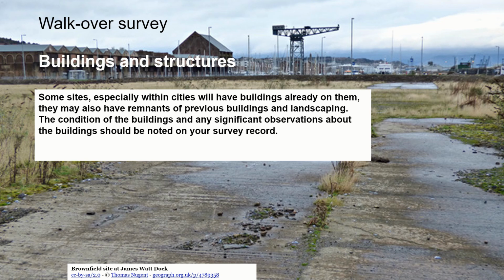There's also, if there's evidence of existing buildings, this photograph's from James Watt Dock in Greenock, and this was an industrial site, and we can see on the photograph there's hard standing areas, there's probably evidence of buildings, so there may be material that needs to be removed from site, which has a cost attached to it. So noting these things down on a walkover survey is useful, and you can make choices about where your building goes based on your observations.